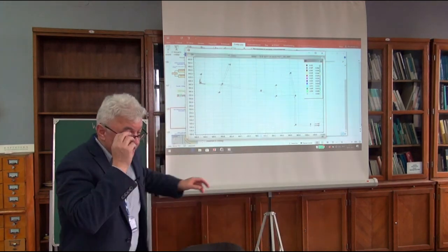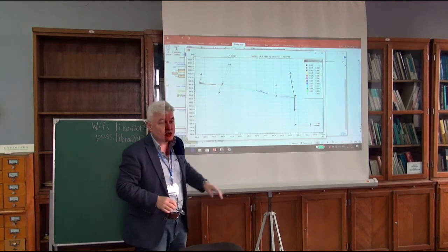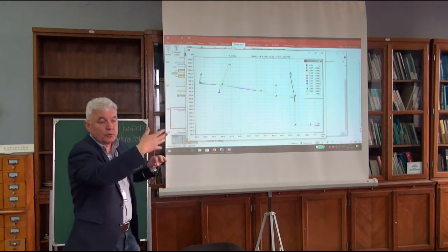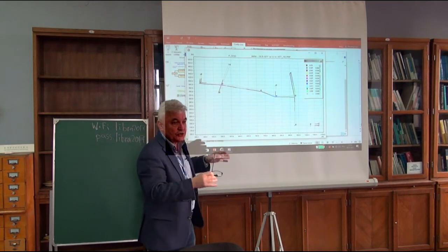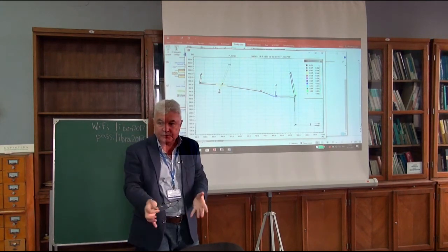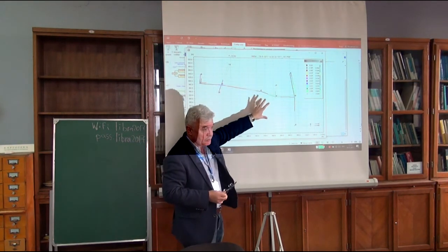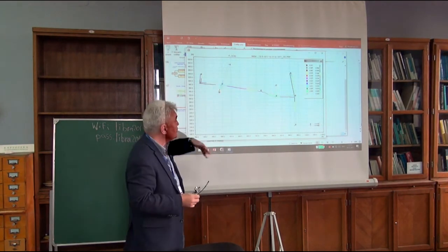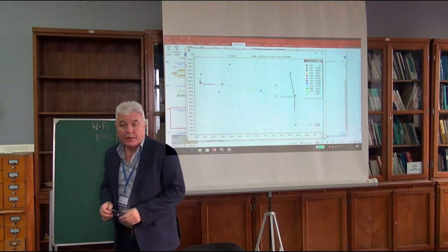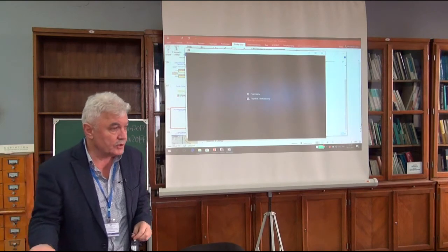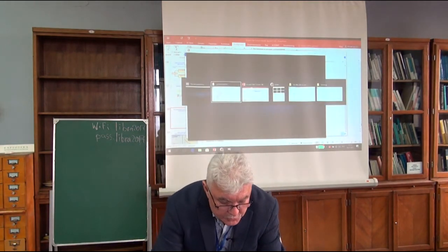So this is real stuff. You see by color, the pipes which are being changed to different diameters are shown. It's just an animation of the optimization process, a simple case of 12 pipes. So a randomized search in the space of all possible diameters for 12 pipes, a 12-dimensional space. For every decision for pipes, we evaluate the quality of this solution, and then we continue. And in the end, we arrive at a set of pipes which would not be too expensive, and which would lead to small flood damage.